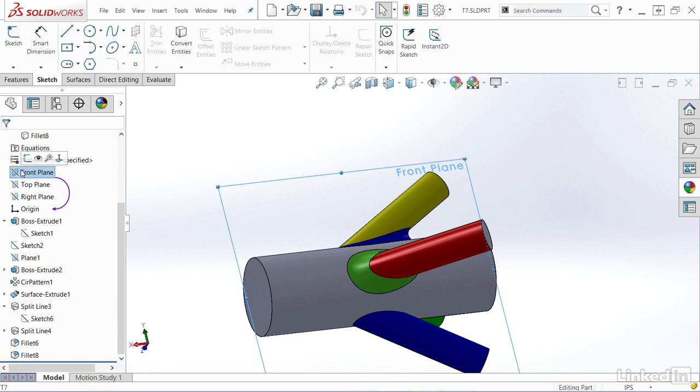I'm going to click on OK, and now I've got this nice line that I'd like to project down to this surface. So I'm going to do the exact same thing, go to Features, Curves, Split Line, and I'd like to project the current sketch down to the surface here. Click on OK, and now you can see I've got that line cutting this surface here. I'm going to take that plane and just hide it for right now. And you can see the two lines which are going to be creating the hold lines for that feature.